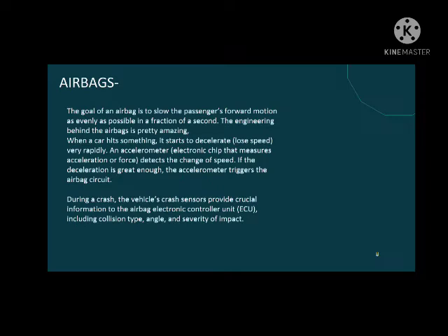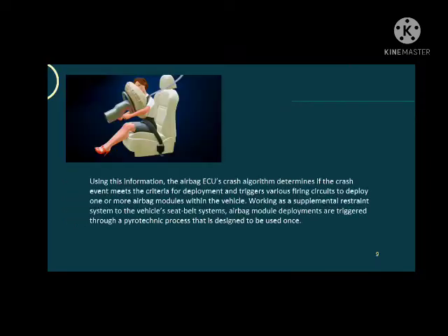A typical airbag will require about 30 milliseconds to inflate, meaning that the crash must be detected within about 20 milliseconds. With respect to the speed of modern digital electronics, a 20 millisecond time interval is not considered short. The complicating factor for crash detection is that many events, like the acceleration and deceleration experienced by the typical car, could be interpreted by airbag electronics as a crash, such as hitting a large pothole or driving over a curb.